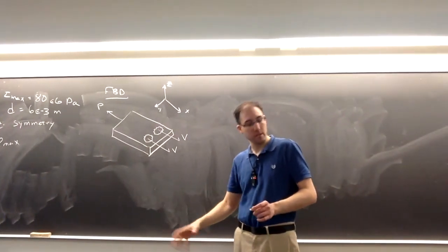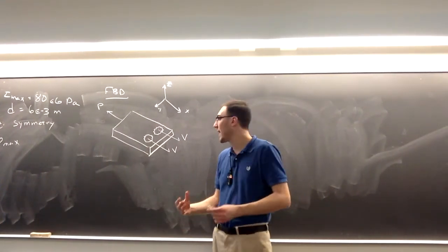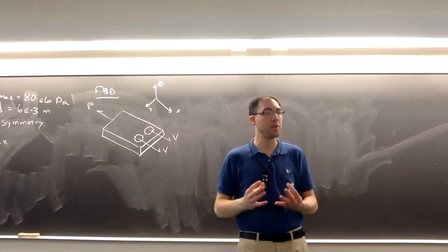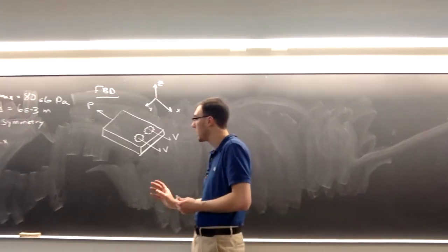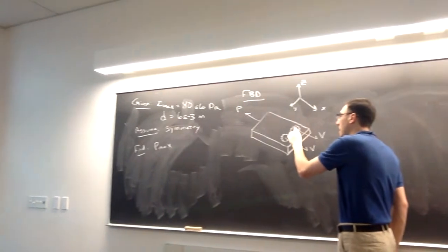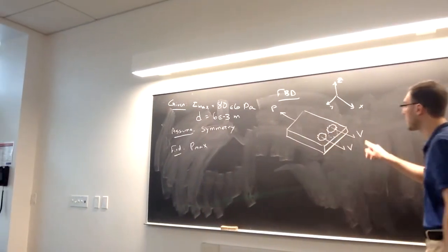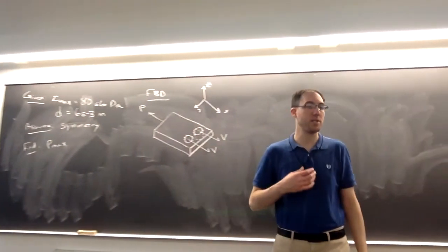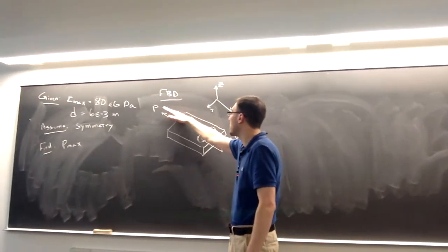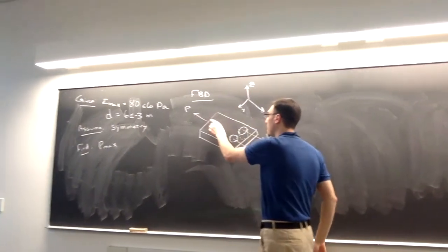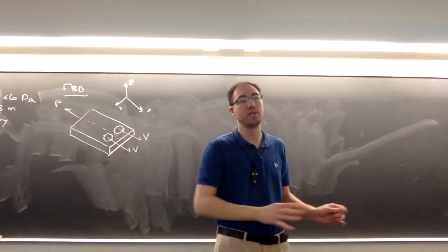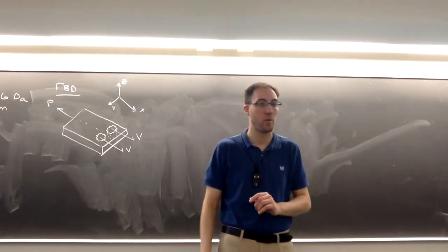In general, and we'll visit this towards the end of the semester, we can have all of the P, the V, and the M non-zero, and all these different stresses acting simultaneously. For right now, we're not going to worry about that, though. All right, so at the top, because of symmetry, I'm going to assume that the shear forces are the same in the two bolts. This would be different if P were not centered between the bolts, then they could possibly be different. For simplicity here, I'm assuming everything's in the center, so they're going to be equal.